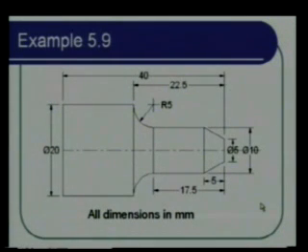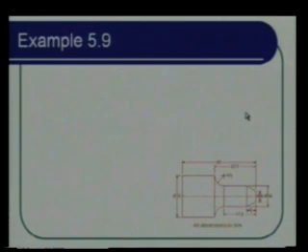Let us say I am not doing the roughing operation, but only the finishing operation here. Okay. So what I have is the circular interpolation here, straight line interpolation, straight line interpolation. So I will have the tool somewhere here, bring it to this point, then go like this, and then come back and then go to the start point. That is the sequence of motions that we are going to have.